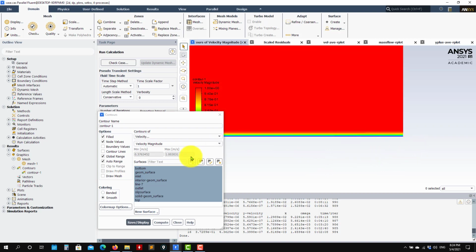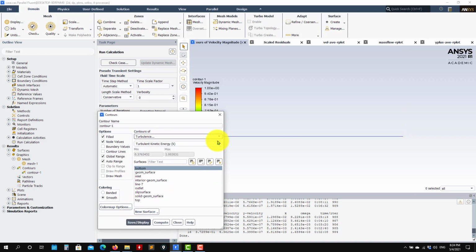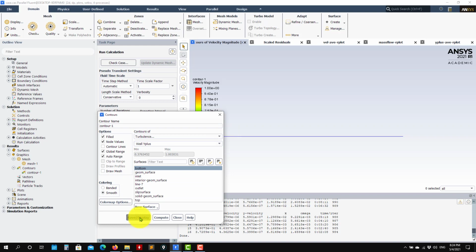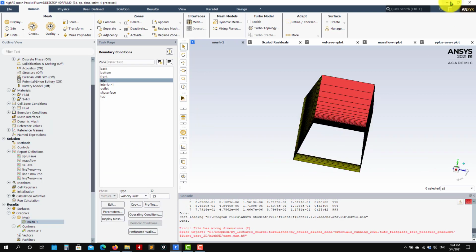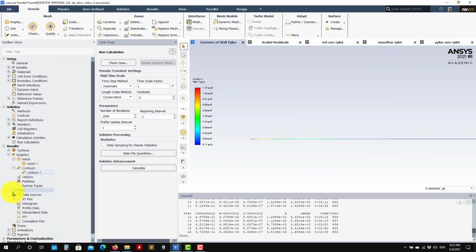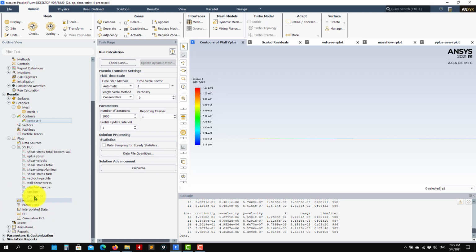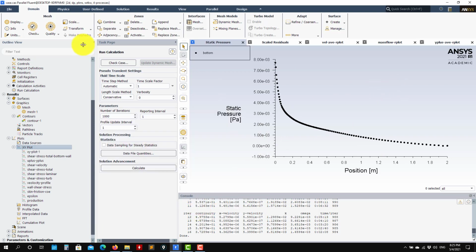So to see whatever you have here, okay, for instance, you have the bottom. Okay, so see that if you want to see y plus there, and put it there, okay, it's not very easy to visualize this. Okay, so as you compare, you have it there, but it's not very easy. As you compare with the 3D, see that it's better to visualize on the surfaces. So in this case, you will need to go here to plots, XY plot, and plot that quantity. Let me go here. And you plot that quantity there, and you have it like this. Okay, so it's up to you.